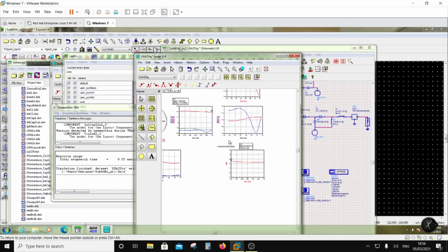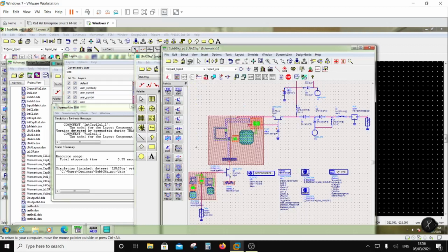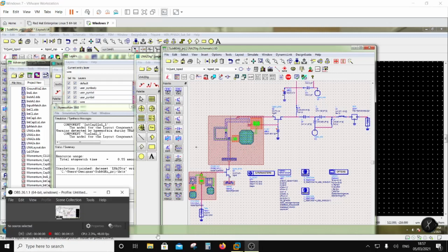So this is the small remedy which I have done here, and now I am going to transform the output stage into the layout. I have to be really careful about what I do over here because this impedance is important. This has to be a very good short here, otherwise there would be an issue of the internal impedance of this supply. So that's all I wanted to tell you.